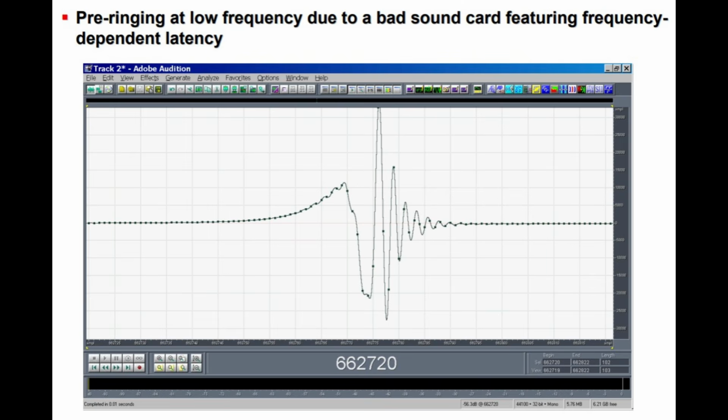In some cases, also low frequencies can cause a significant pre-ringing. This is shown easily employing a loopback connection. That is, connecting a wire directly from the output to the input of the sound card. The following figure shows the result of a loopback measurement, employing the same parameters as for the previous example.